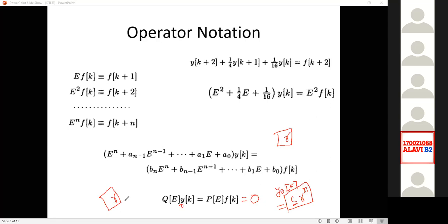So can you identify the restrictions on gamma for stability? It should be from 0 to 1. That means it must be less than 1. If it is 1, then it will remain constant. So it must be less than 1. If it is greater than 1, then what will happen? As we have an exponent there, the system will be unstable as time grows.